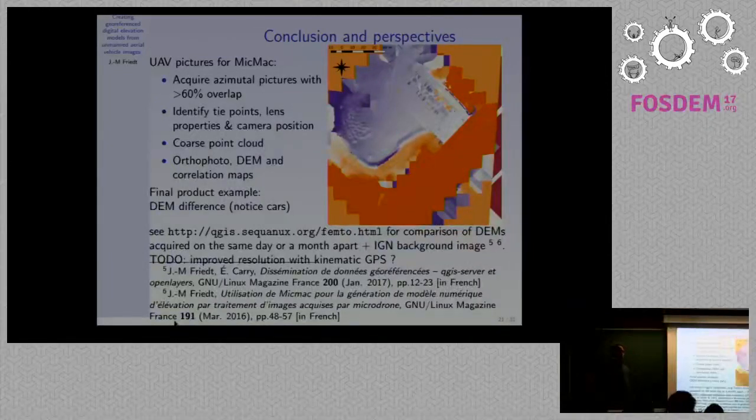In the moraine here, from 2 measurements done from 2 days apart, I get about 60 centimeters. So my current interest is whether I could measure snow cover thickness. 60 centimeters is at the threshold of what can be usable. One of the main reasons of this poor resolution in northern Spitsbergen compared to what I did in the parking lot is the poor alignment of the 2 DEMs.